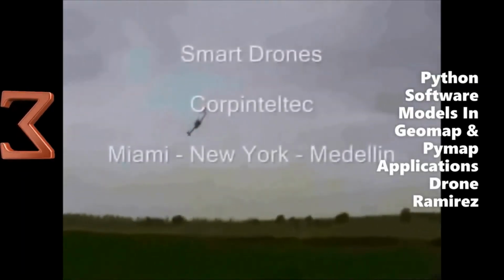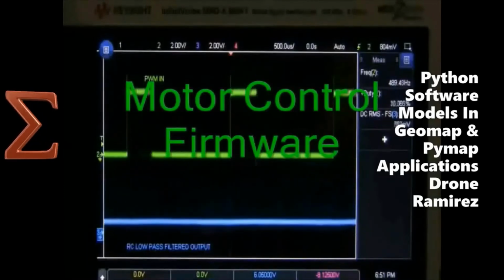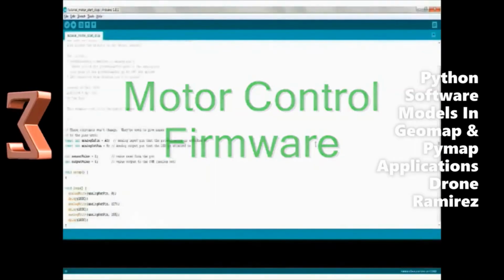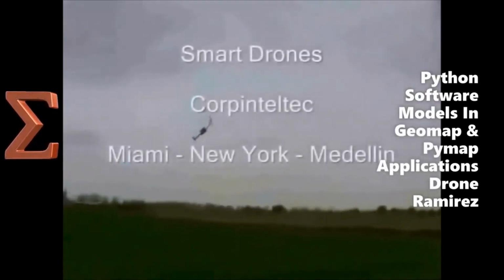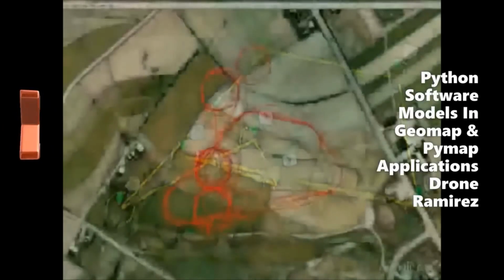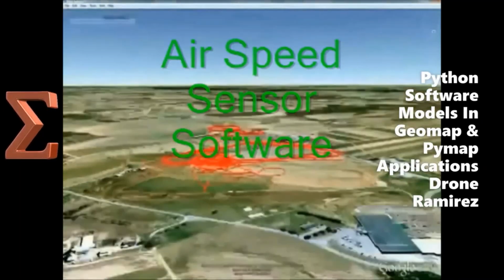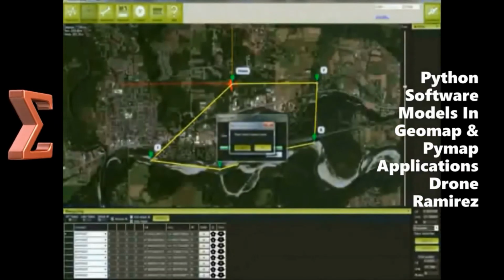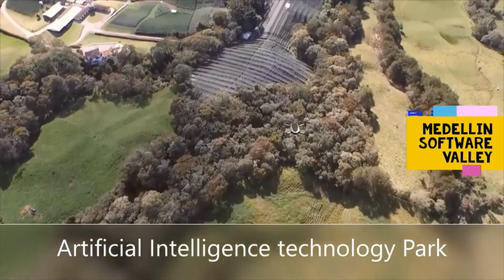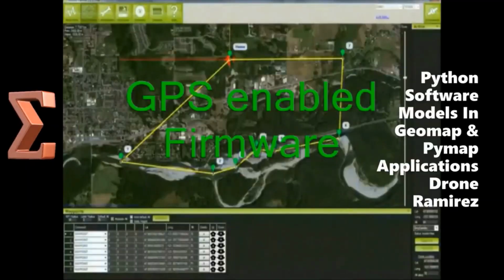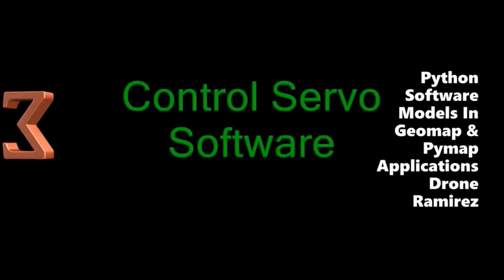In addition, telemetry logs are recorded and saved automatically on your laptop during each flight and after every flight. The airspeed sensor system allows for control of the drone based on airspeed instead of the ground speed, which comes from the GPS readings. The autopilot is connected between the RC receiver and the control servos.